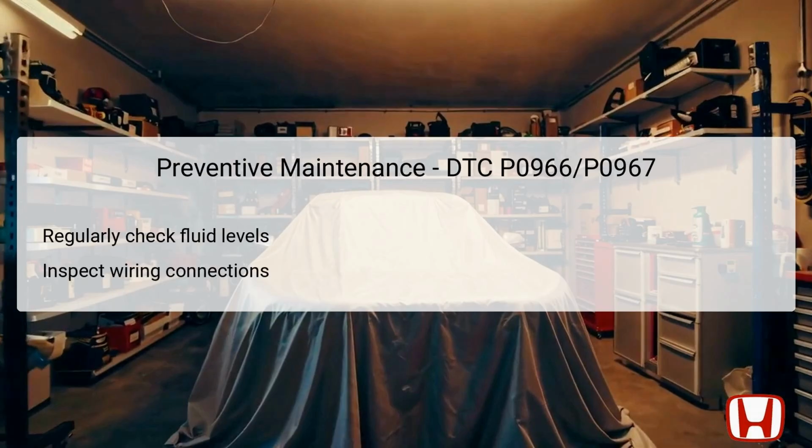To prevent future occurrences of DTC P0966 and P0967, implementing routine maintenance practices is essential. Regularly check the transmission fluid levels and ensure that they are within the recommended range. Low fluid levels can lead to erratic transmission behavior and premature component wear.